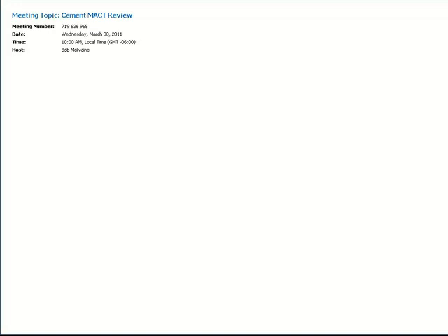Okay, so what you're saying is the instrument doesn't care what the particulate size, shape, makeup, chemical composition, or anything is, correct? That's correct. We don't care what it is, if it's calcium-based, silicon-based, carbon-based. Those particles absorb beta and attenuate the signal strength, and that's what we look at: the reduction in beta strength from the clean filter tape to the dirty filter tape. Okay, thanks. You're welcome. Yeah, I think that's an important point. Other questions?